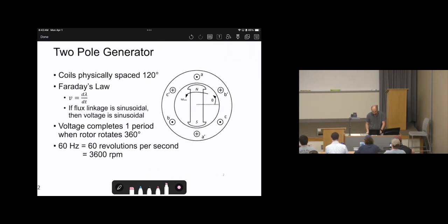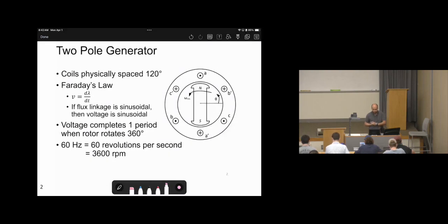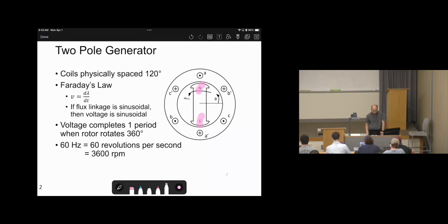That's how the structure looks. Since it's three-phase, and this is what we call a two-pole machine, we have one north and one south. We will take that complicated device that we see here and reduce it to look at the steady state and the electrical structure. We don't want to discuss other impacts, assuming everything is working fine. So what we are worried about is just this part. This is not 100% true, but I'm focusing on this, assuming the other factors are constant and can be negligible.